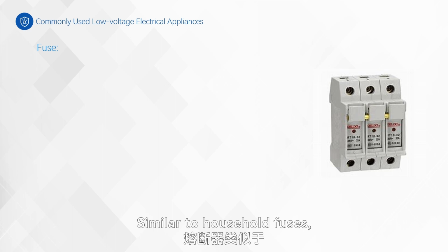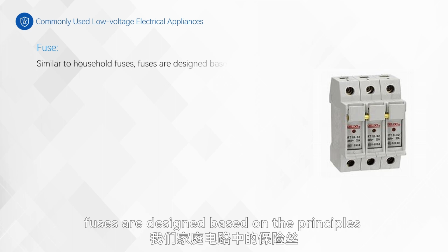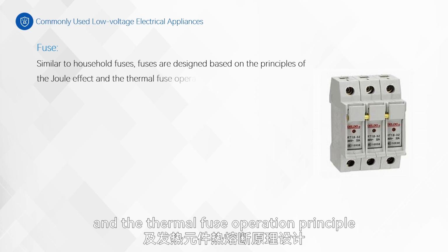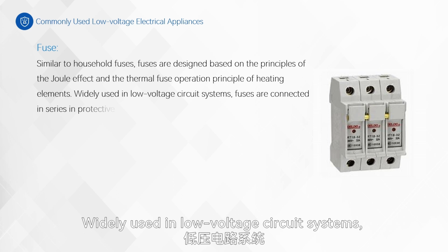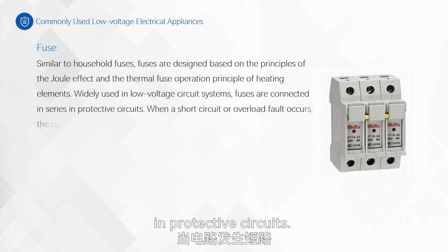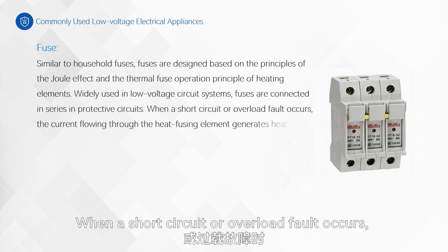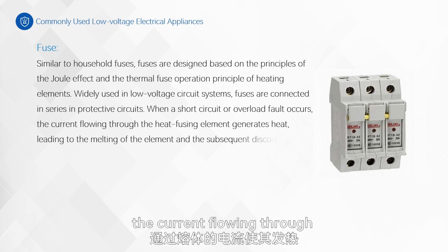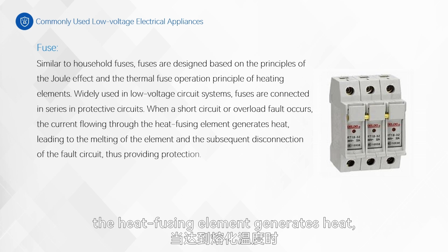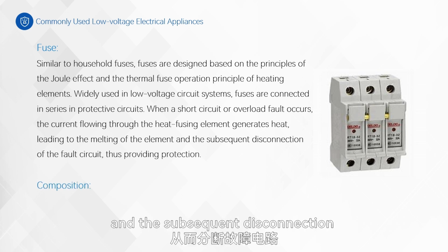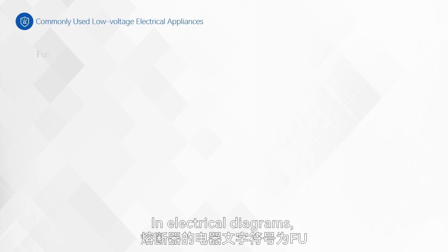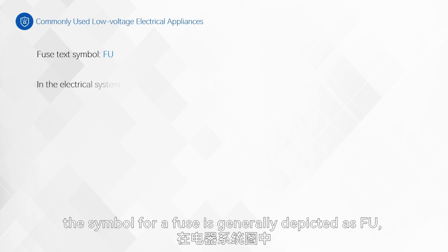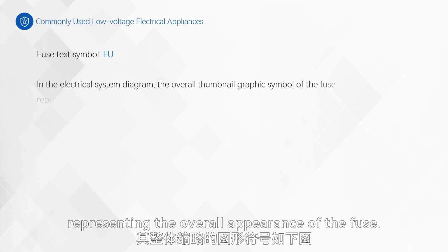Similar to household fuses, fuses are designed based on the principles of the Joule effect and the thermal fuse operation principle of heating elements. Widely used in low-voltage circuit systems, fuses are connected in series in protective circuits. When a short circuit or overload fault occurs, the current flowing through the heat fusing element generates heat, leading to the melting of the element and the subsequent disconnection of the fault circuit, thus providing protection. In electrical diagrams, the symbol for a fuse is generally depicted as Fu, representing the overall appearance of the fuse.